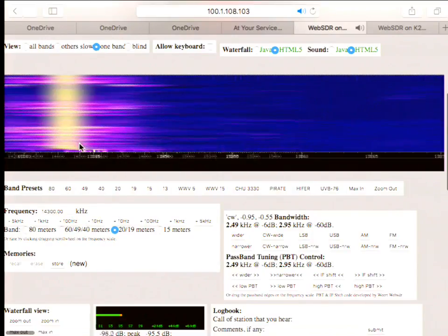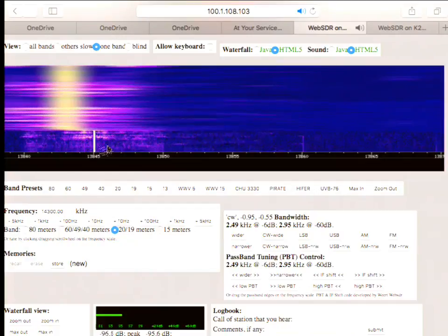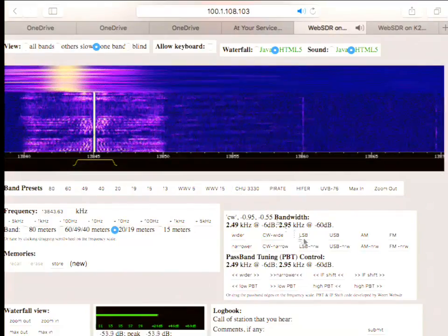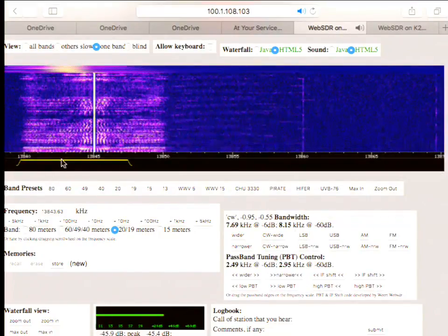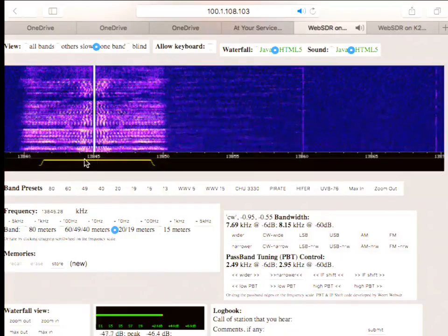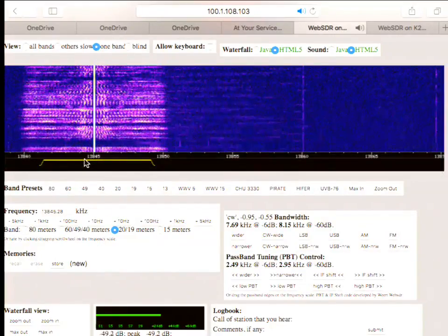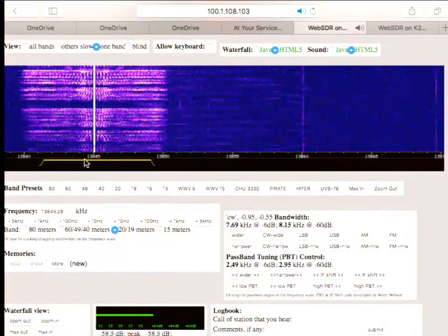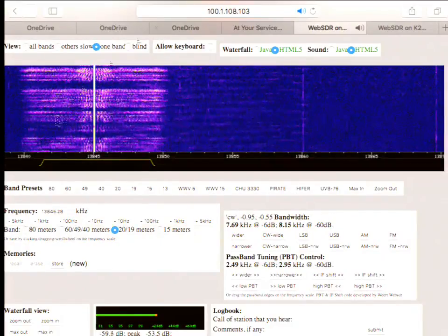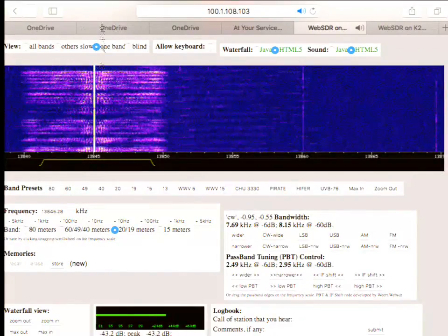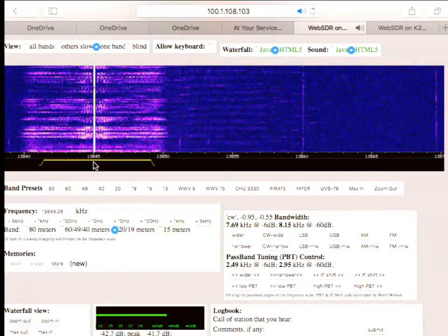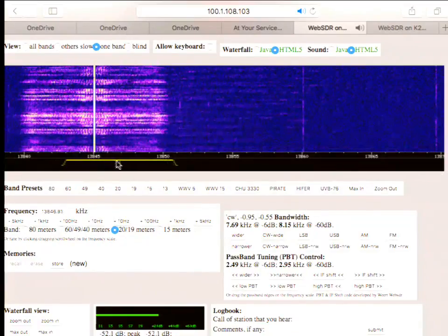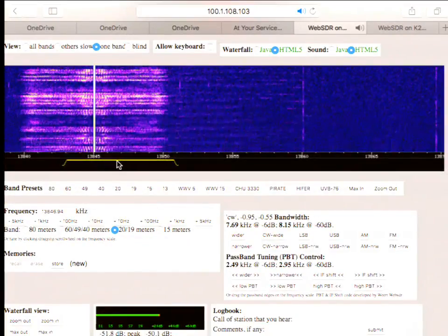And the signal over here that you see, I'm going to zoom in. It has a carrier. And it's actually amplitude modulation. Okay? This is, I think, some religious shortwave station. But you see the double bands, the double sidebands, and the carrier. It has a carrier. Okay? Now, if I move the demodulation a little bit off band, do you see a difference? It's pretty robust. So for that wasteful energy, I get some robustness to it.